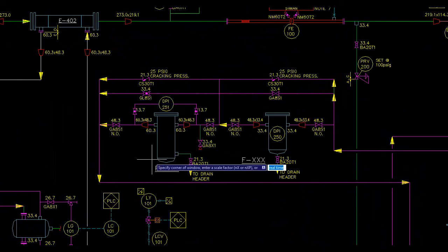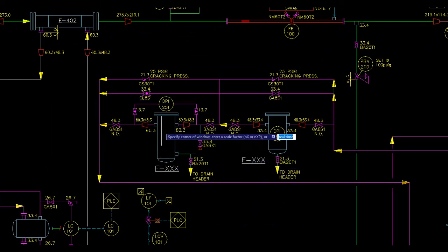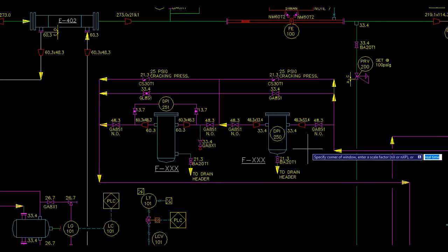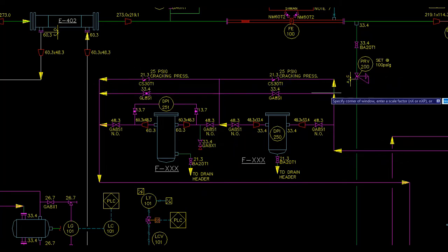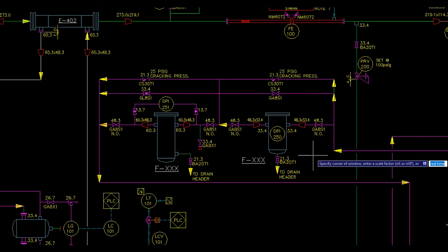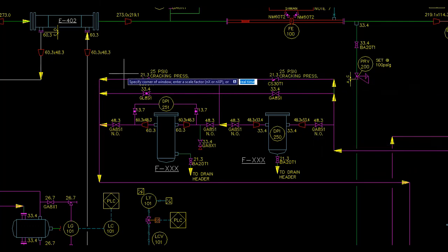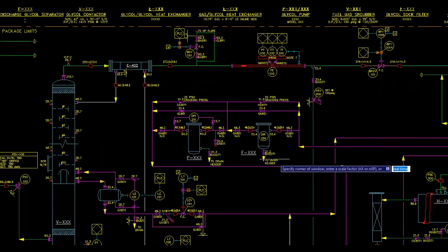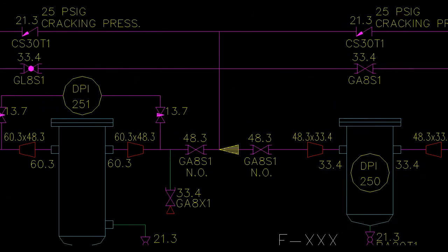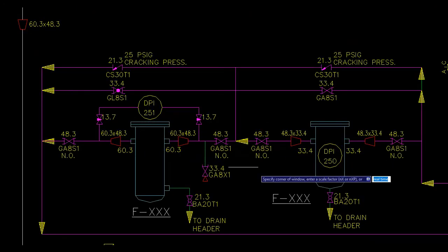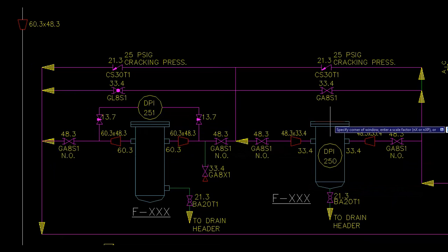Usually in a clean gas, there will not be any particles, and glycol is a poor absorber of hydrocarbons. So these filters are bypassed using this bypass arrangement. It's not bypassed all the time, but it's at the operator's discretion when they want to change out the filter elements, and then they can bypass it. One aspect to remember is to depressurize the filters before they can be opened for servicing or changing the cartridge. There are many incidents reported for not following that procedure.